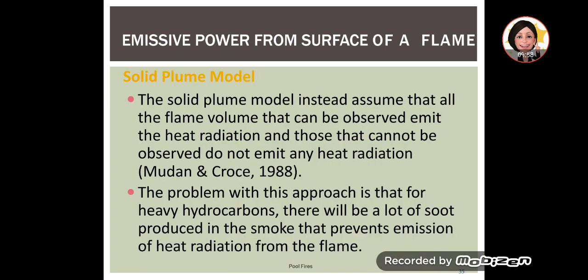Then we have the solid plume model. Instead, assume that all the flame volume that you can observe emits the heat radiation. So whatever flame part you see will emit heat radiation, and the parts that you cannot see and cannot feel, we assume there is no radiation from them. Okay.